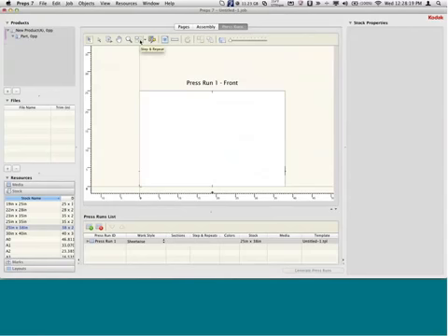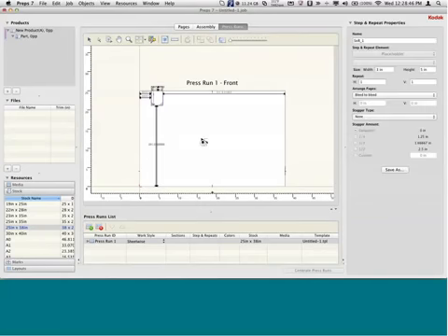So previously, with step and repeat, you clicked on it, and you got a sub-menu that allowed you to go in and control your step and repeat function. And that was great, but it was a modal capability. Once you did it, you were done. Now with step and repeat, I've clicked on it, and you'll see here in a second on the far right, we will get step and repeat properties. My tool, I can click and drag. You see my step and repeat icon. And on the far right, I have access to my step and repeat properties.